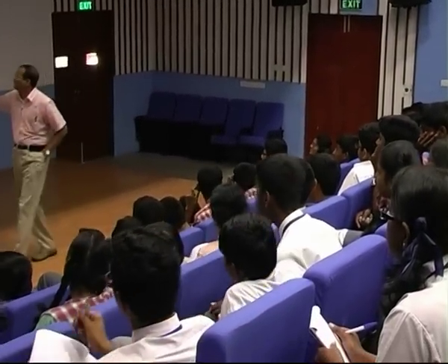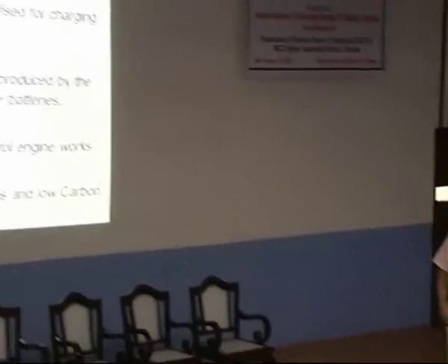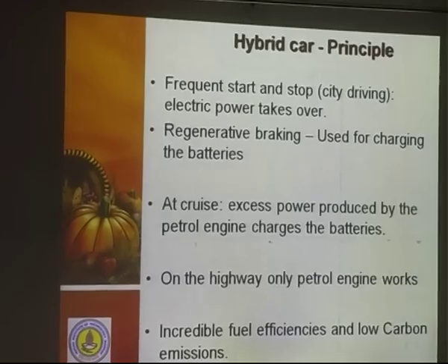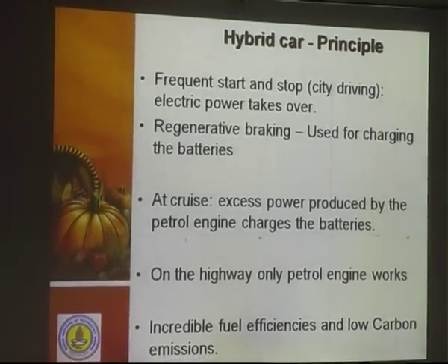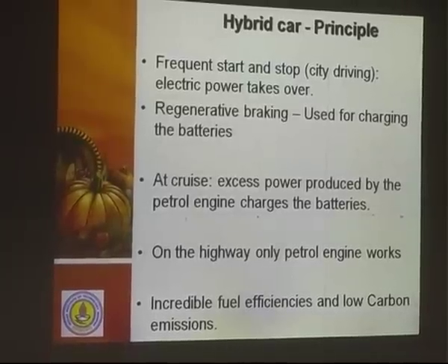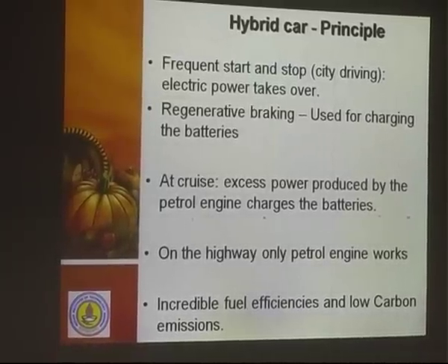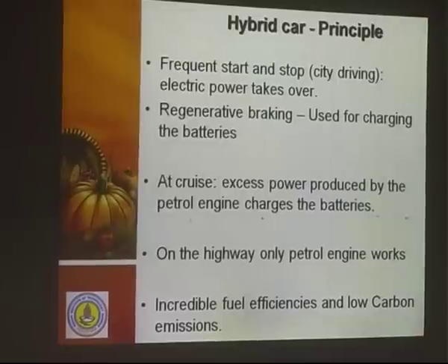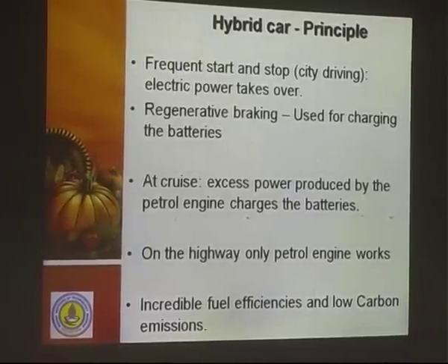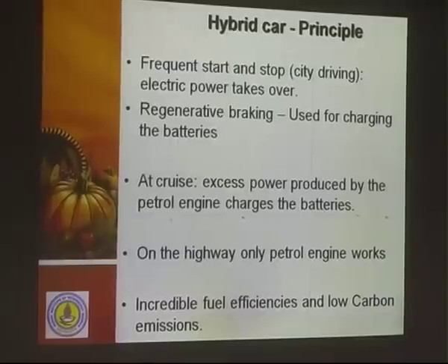Okay, now. What is this hybrid car principle? When you are frequently starting and stopping in city traffic, the electric power takes over. The regenerative braking: when you are braking, the excess power can be used for charging the batteries. At cruise, excess power produced by the petrol engine charges the batteries. On the highway, only the petrol engine works. So incredible fuel efficiencies and low carbon emissions.